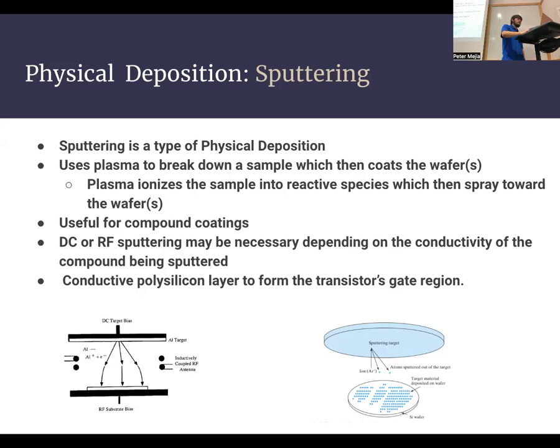Yes, okay, cool. And then the main difference is that chemical vapor deposition is more chemical in nature, so the material gets deposited everywhere, even in spots that are not visible to the gas source. And then physical vapor deposition is a very line of sight process. Mhm, that makes sense.